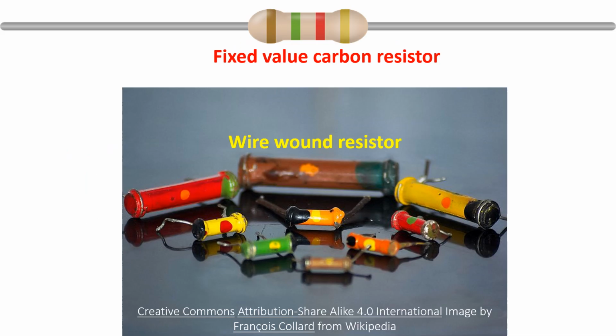Two important types of resistors are wire-wound resistors and carbon resistors. The resistors illustrated earlier are carbon film resistors, the resistance value of which depends on the amount of carbon present in them. Wire-wound resistors can be made of nichrome wire and usually have higher power rating. Variable wire-wound resistors have been conventionally used in rheostats, which are variable resistors with a sliding contact.